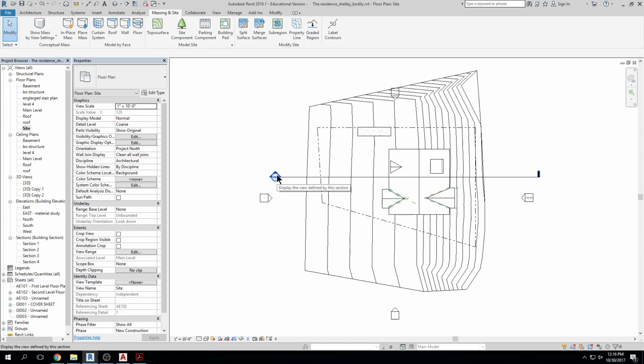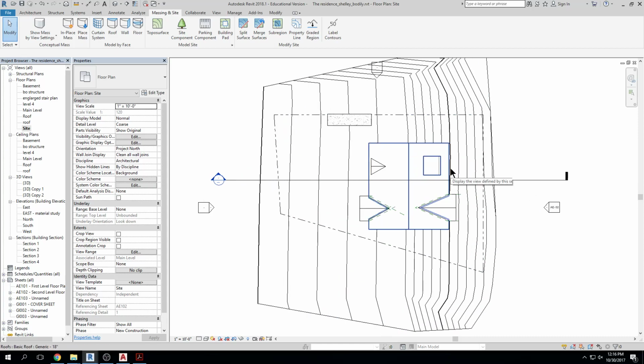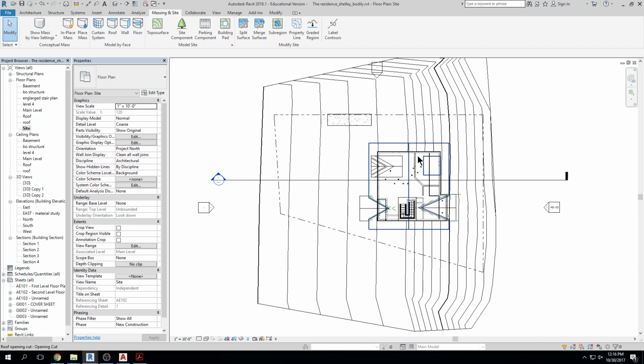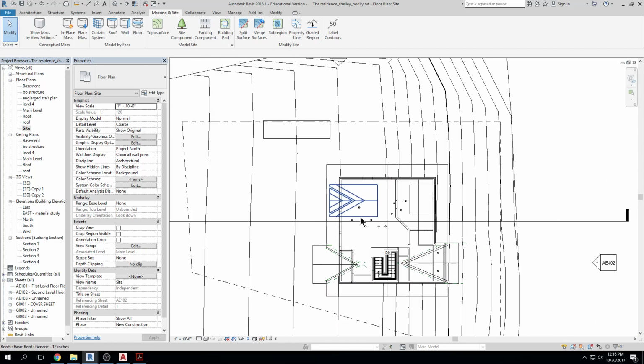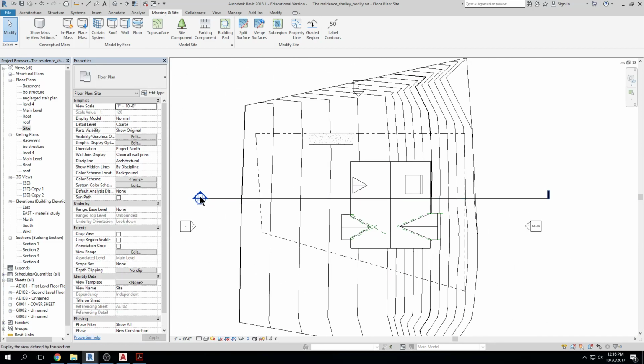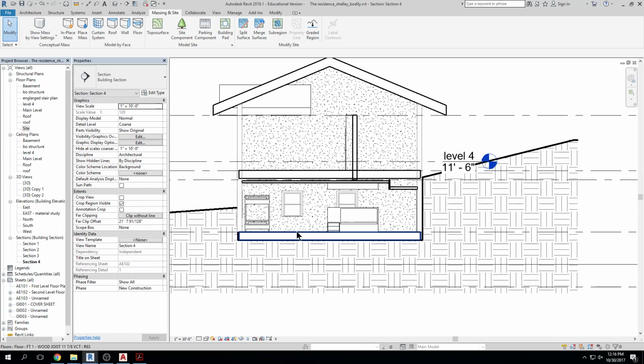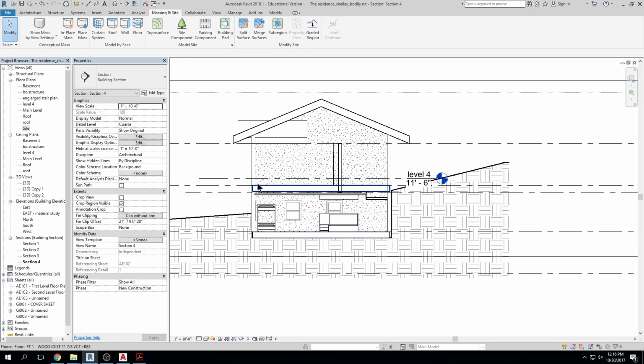You're going to have to add a building pad, right? So once you have your topo surface in here, you will switch to a wireframe, WF, view, or you will hide the roof, so that you can draw the outline of the building pad all the way around the object, okay? And you want that building pad to sit wherever it's appropriate in your project. We'll get basements in there this week, so you may have to move it, but wherever it's appropriate so that your topo surface is filtered out from your project, okay? Makes sense.